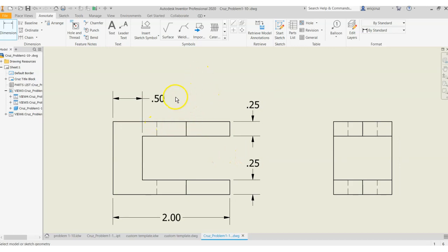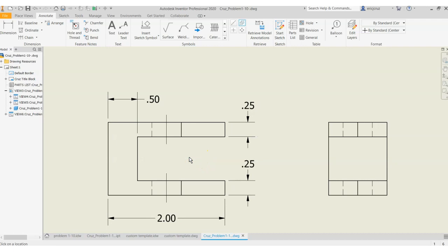So the center lines, there's a hole here. Remember, there's a hole here. So we're going to click on center line bisector. Click this edge, and you're going to get a center line right here. That center line is terrible, but we're going to fix it once we have the other center lines in place. This center line, this center line. Okay, we're going to fix those in just a few. I might forget. Let's do that now, actually.